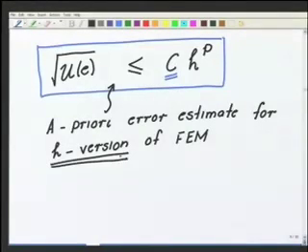There are two or three various approaches we can take to reduce the error. So our job is to get the finite element solution as close as possible to the exact solution. We can achieve that goal through different approaches. One approach that we have taken is we have fixed P, we have only refined the mesh, so this is called the H version. That is, only H is changed, the parameter H.